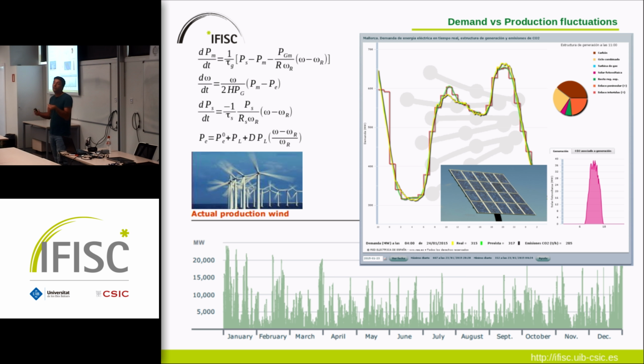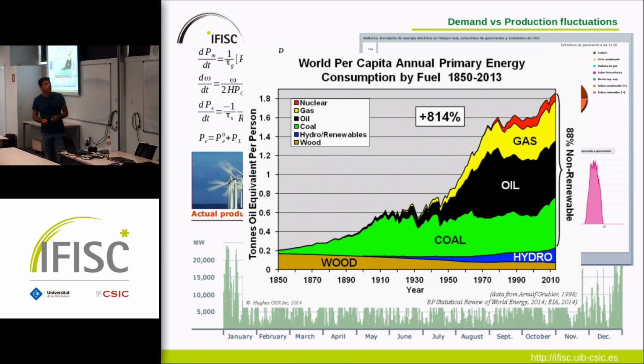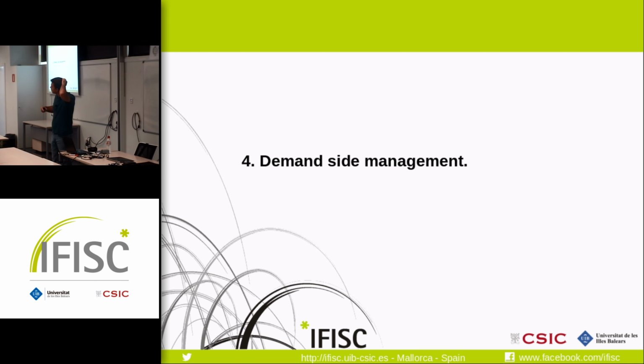So you have a real problem here with the control, because the power plants, which are supposed to do the controlling, are now fluctuating too. Dealing with that is complicated. You will need huge reserves, because when the wind goes down, you have to switch on a machine that produces, all the time changing. So that's a problem, and that's why we somehow need to change the control procedure.